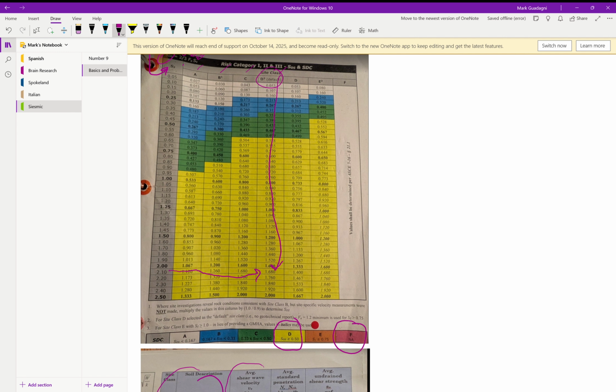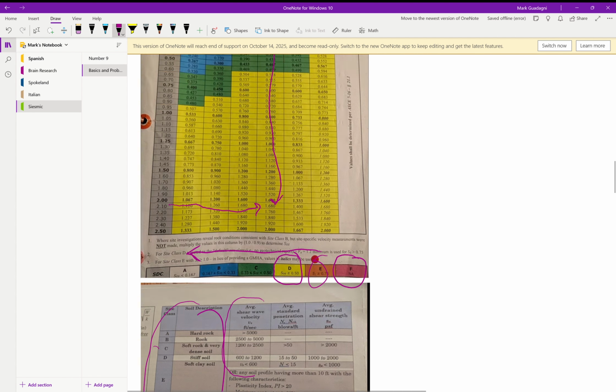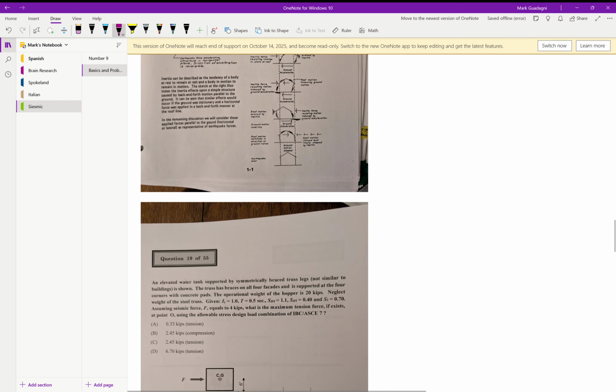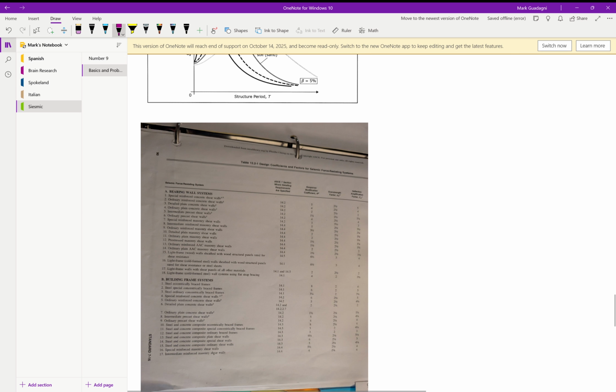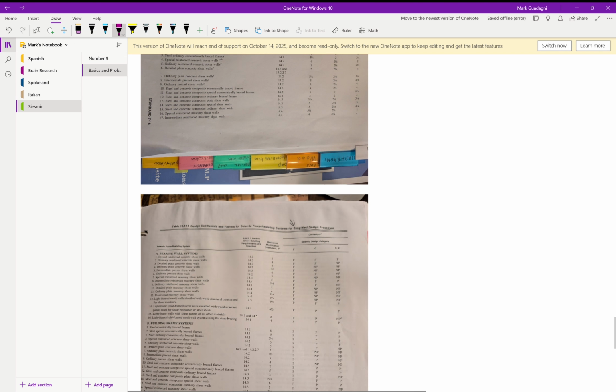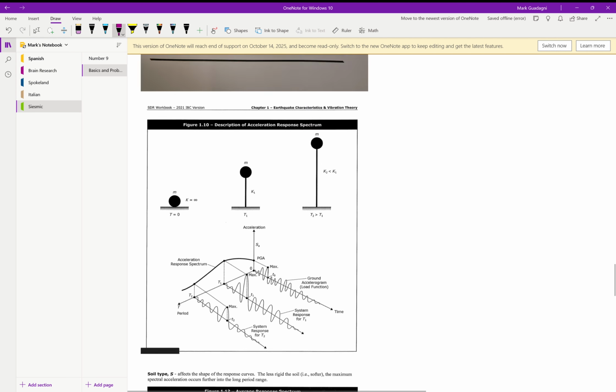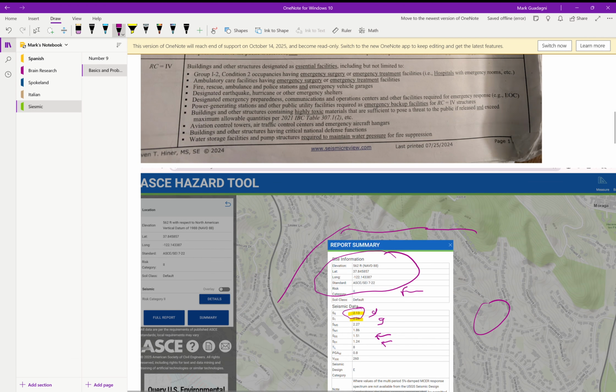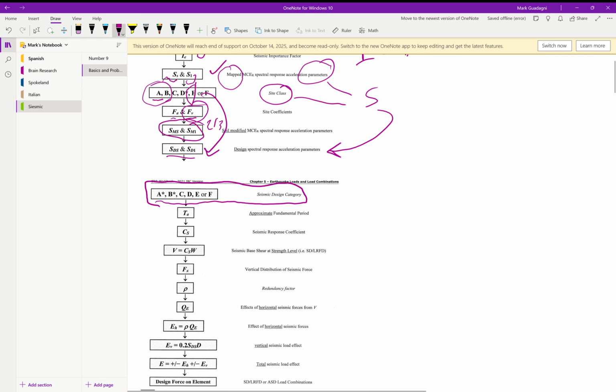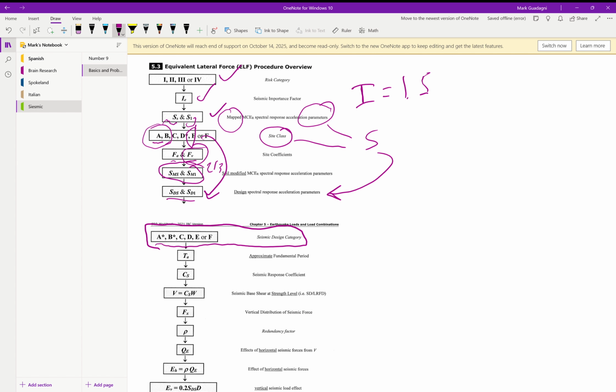Like you can't have eccentrically braced buildings with a whole bunch of irregularities and stuff like that. So ideally, the closer you are to A, the more flexibility you have in your building. But if you start getting into the higher seismic design categories, you can start getting limitations such as the height of your building, etc., etc. I cut that off in there. But anyhow, so now we have that.